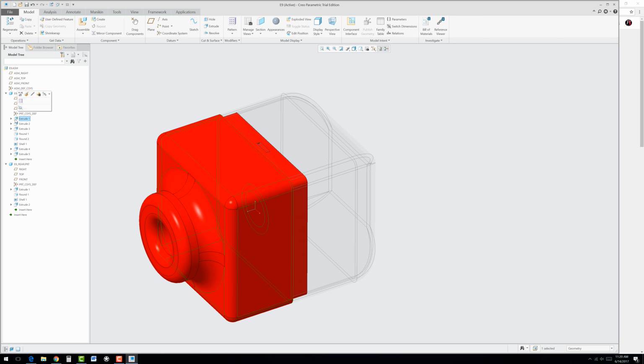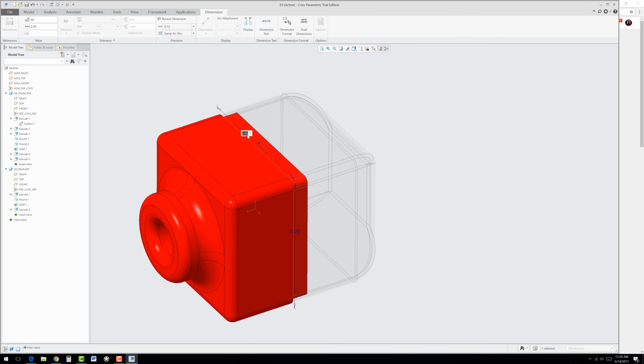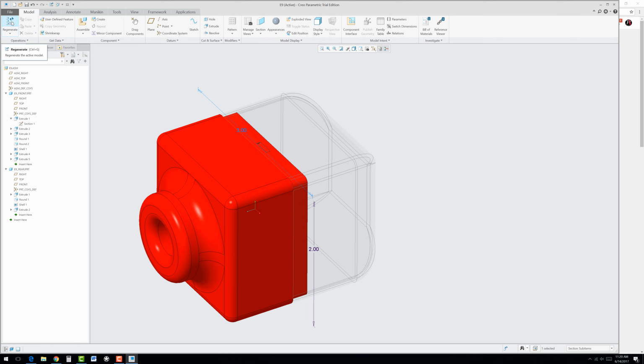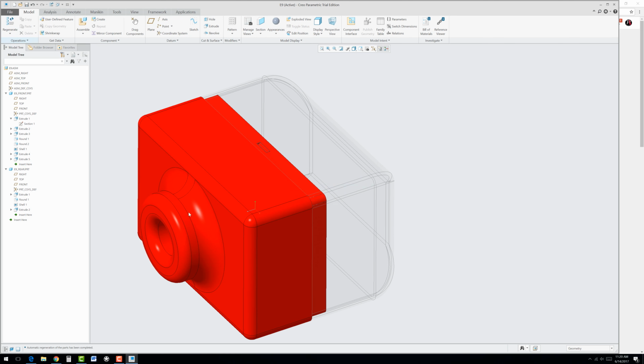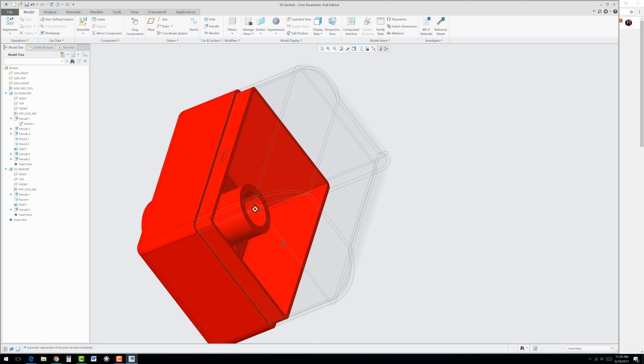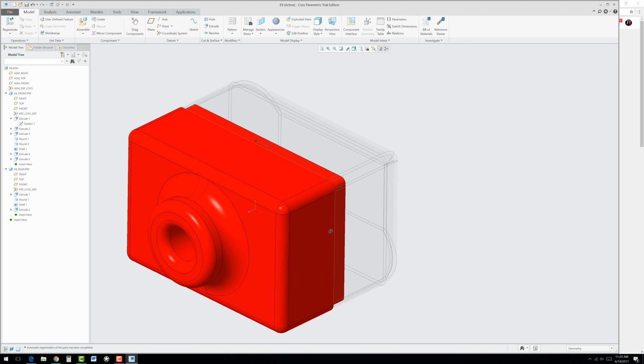And that first extrude. There's our sketch. If we click on Edit Dimension, it should bring the dimensions up. And now we could double click on that. Let's say we want to make it 3 inches in width. And once you get that, click and now hit Regenerate. And there we are, both updated to the new size.